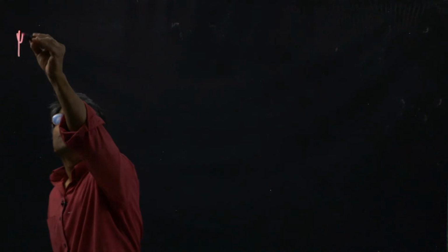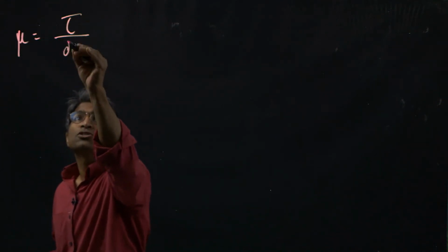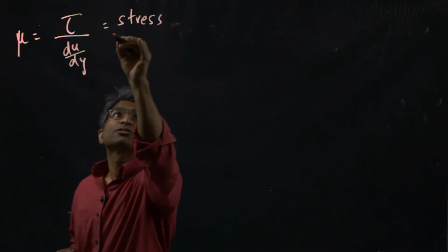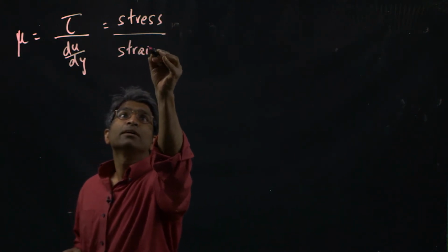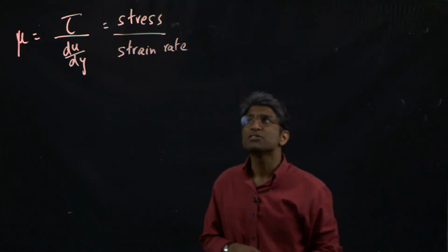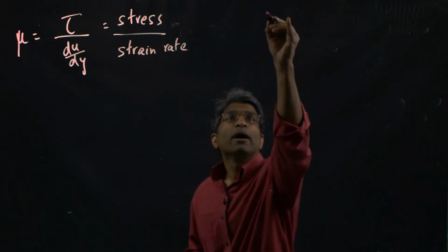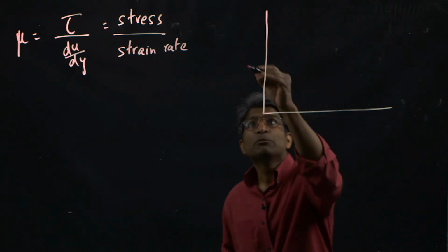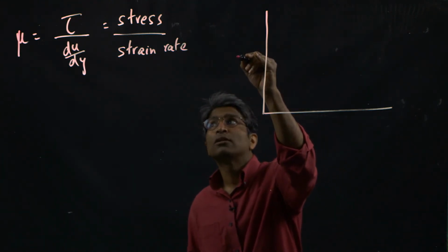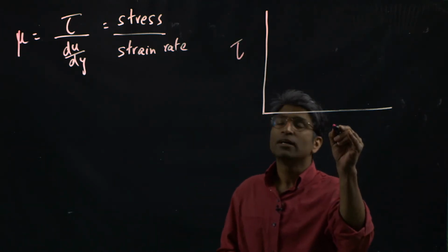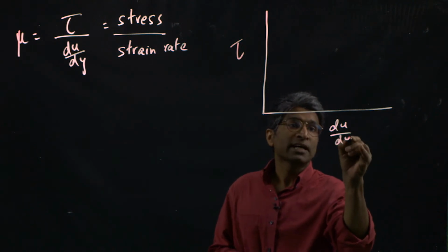So recall that if the viscosity is a proportionality constant between the shear stress and the strain rate, we have a strain rate unlike a strain that you encounter in solids, but conceptually it's the same. If you recall your deformable body mechanics, we typically plotted stress on the y-axis and the strain, in this case the strain rate, on the x-axis.